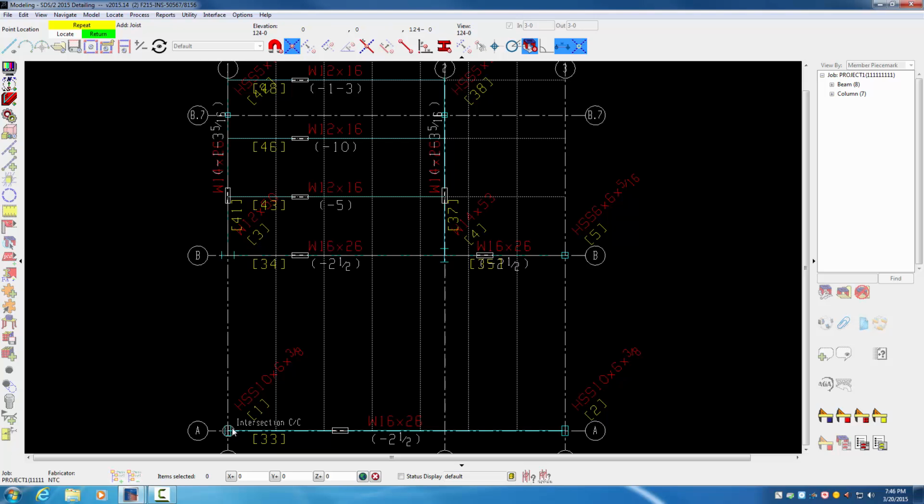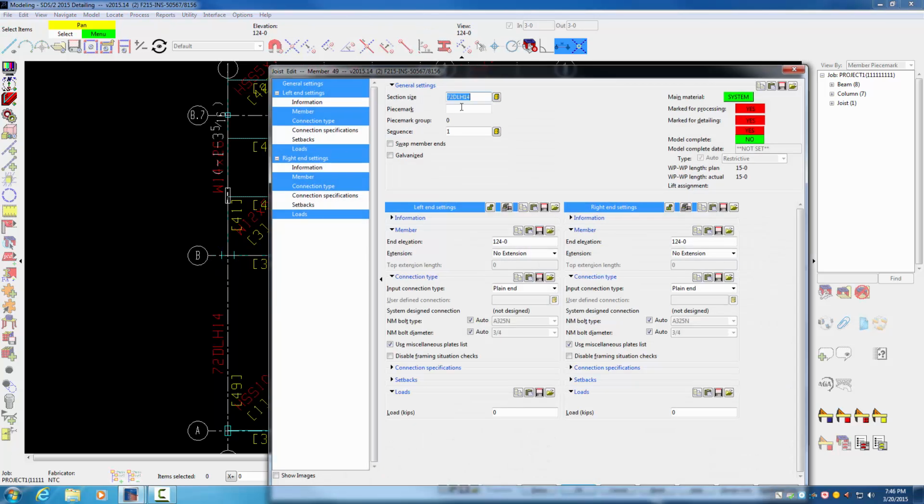So this bar joist, we're going to go from grid line A and 1 intersection here to intersection at B and 1. And for a bar joist, first thing we're going to do on the top of the screen, the size is a 14K3. Again, piece mark and all that stuff you'll leave as is. SDS2 does not detail bar joist,